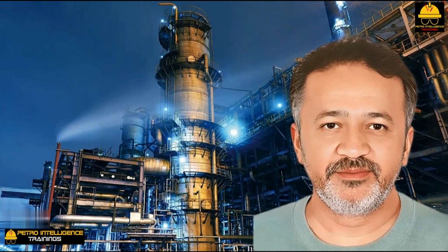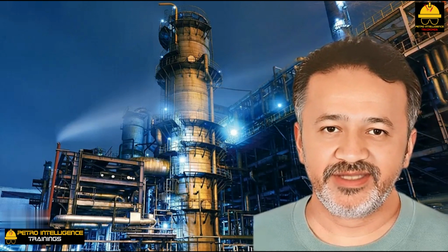I also believe that this explains a problem that I've seen several times in steam turbine exhaust vacuum surface condensers. That is, an apparent large loss in the steam heat transfer coefficient due to a relatively small air leak into the vacuum surface condenser's shell. To summarize, the two most common malfunctions of a steam condenser or radiator are condensate backup and non-condensable accumulation. And these two malfunctions are also the most common problems we encounter in the design and operation of shell and tube heat exchangers used in total condensation service for hydrocarbons, as well as for steam.